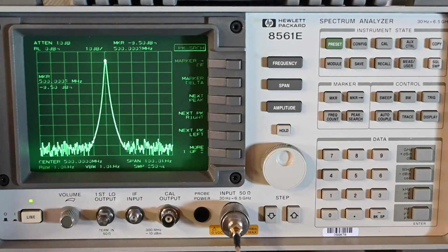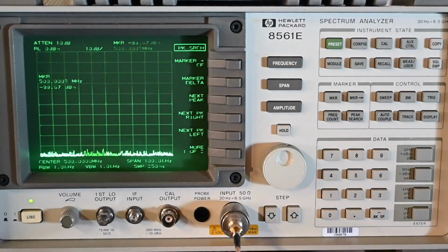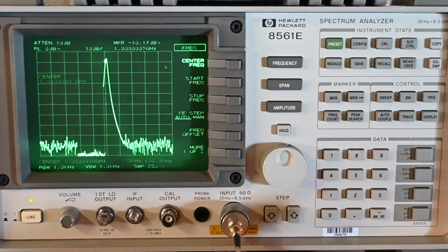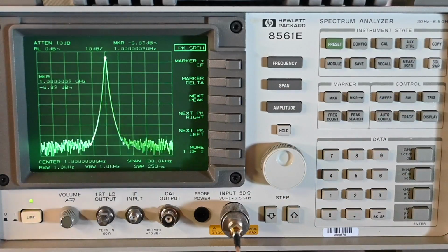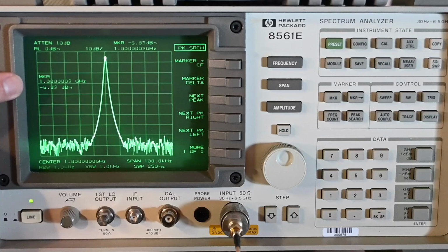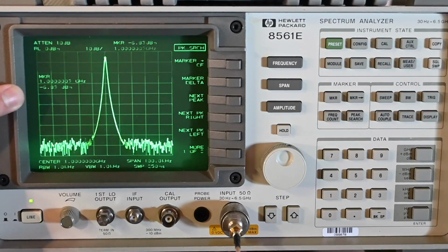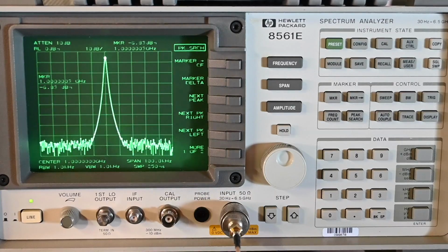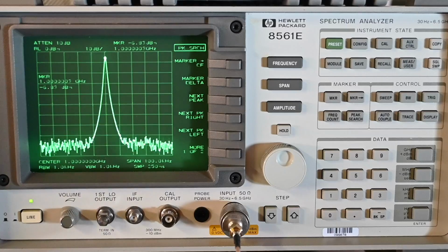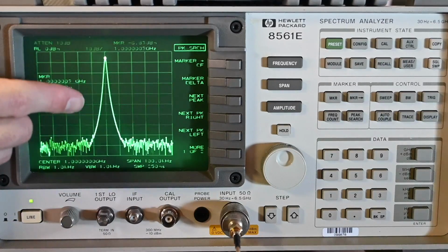So now let's jump up to, say, 1 gigahertz. So frequency over here on this signal generator, 1 gigahertz. Frequency 1 gigahertz. Peak search. And now you can see that the level right there is minus 6, looks like 83, so minus 6.83 dBm. So getting closer to that 0 dBm value. So as the frequency is increasing, the accuracy is improving.